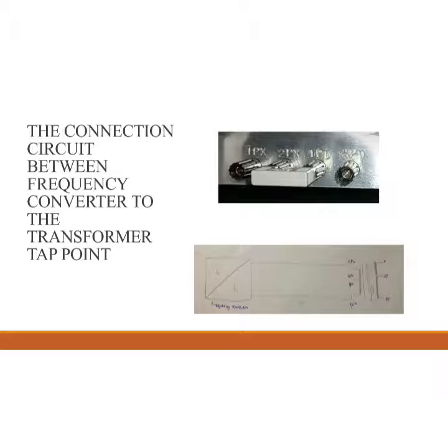I will explain the connection of the circuit between the frequency converter and the transformer tap point. During the connection, we must ensure that the grounding mesh is in contact. Next, we must ensure that the instrumentation connection in the frequency converter is grounded as well.